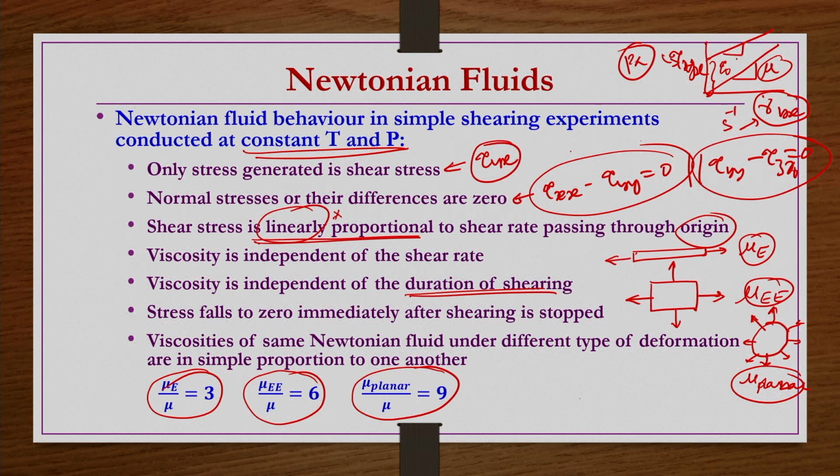Once the yield stress is passed, then the material is deforming. But the viscosity is not changing after this tau naught, while before that it has effectively infinite viscosity. So, it is changing only 2 times. Initially it has a very large, effectively infinite viscosity, and after that it has a constant low viscosity. So, that is also one type of non-Newtonian fluid, right.